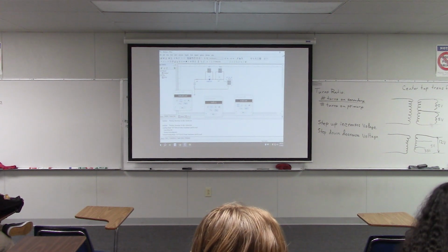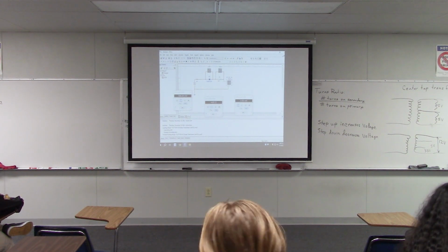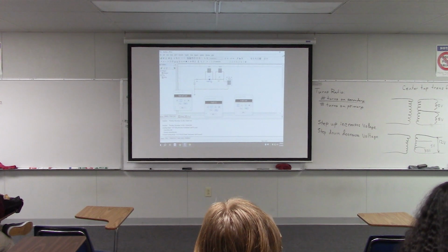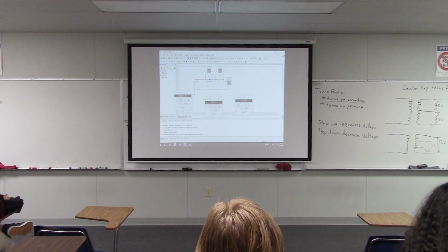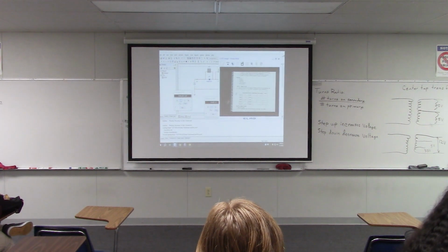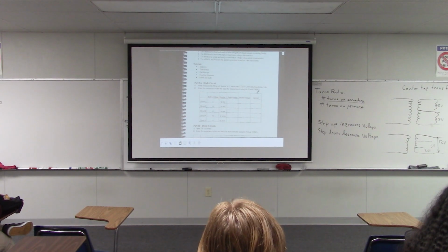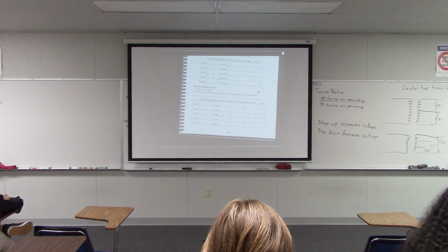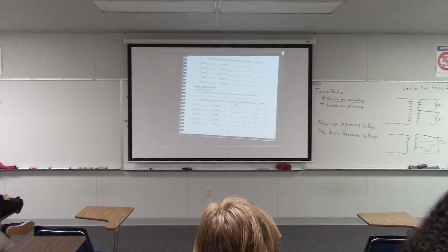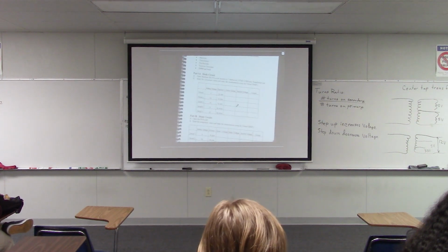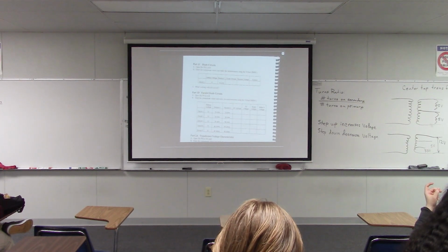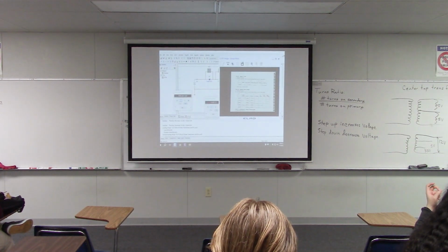So you're going to change the voltage around in the power supply. You're going to change the resistance around and see, hopefully, that the voltage across the diode is not going to change very much. It might change a little bit, but it's going to be approximately the same. Okay. Now, the next table is going to be a very similar circuit, but this one is going to have 2 diodes in it. So you're going to look at that. And then this asks you to open a third circuit here. So let's take a look at this third circuit.